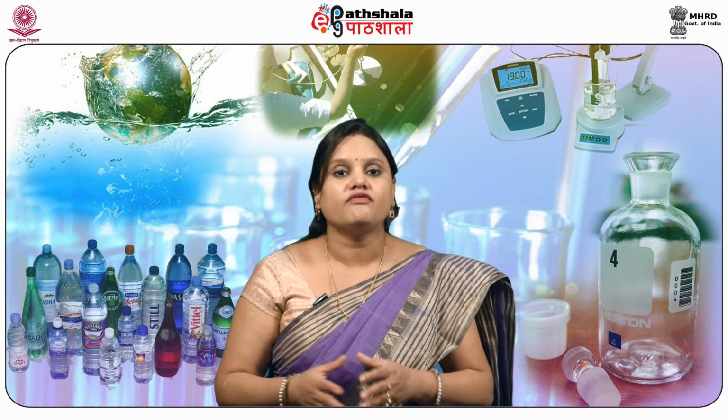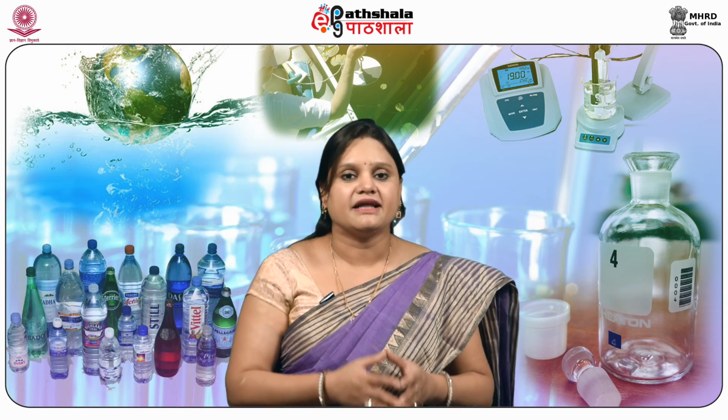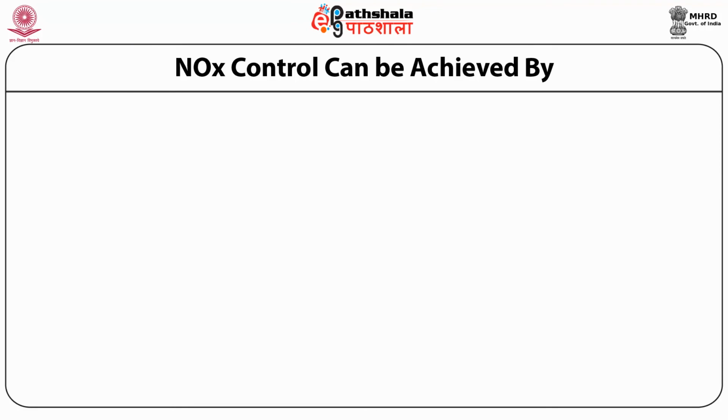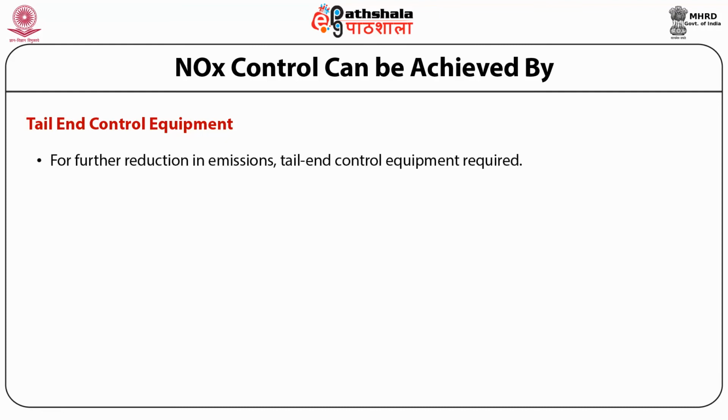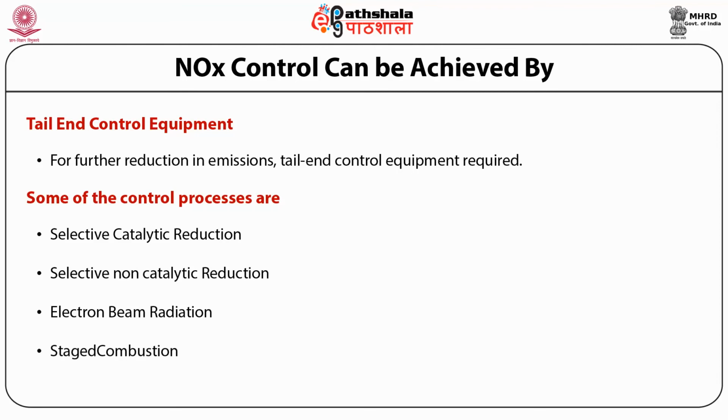This method uses a catalyst to cause the combustion to occur below the nitrogen oxide formation temperatures, which can provide a suitable means of limiting temperature. NOx control can be achieved by tail end control equipment. The combustion modification and the modification of operating conditions provide significant reductions in NOx, but not enough to meet regulations. For further reduction in emissions, tail end control equipment is required. Some of the control processes are selective catalytic reduction, selective non-catalytic reduction, electron beam radiation, and staged combustion.